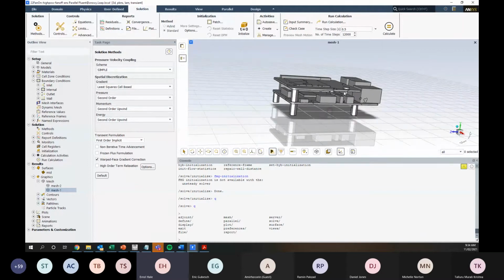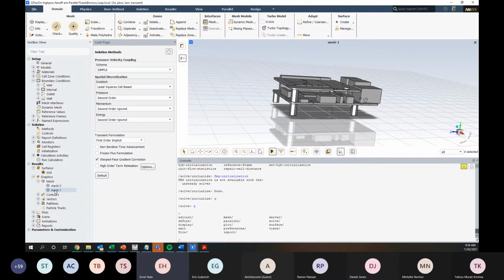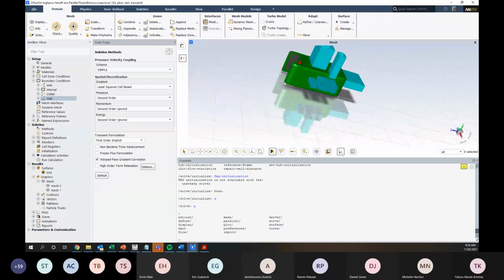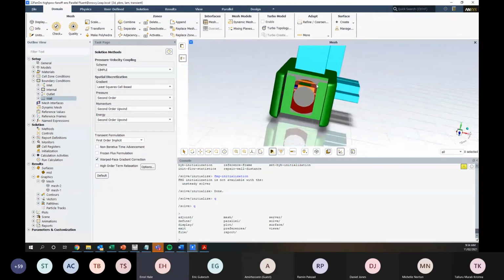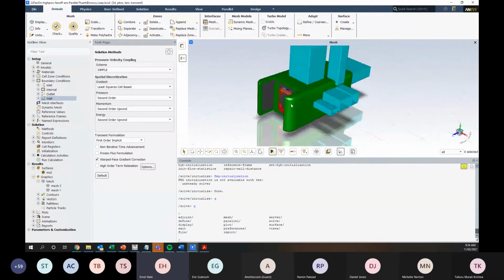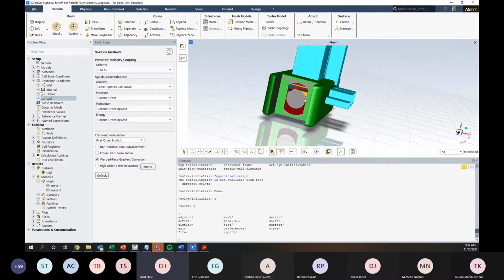So what we did is we built the CAD model of the case with the Raspberry Pi inside, and obviously we generated our mesh, and our domain looks like this. We've got all of our solid components and our fluid domain, and you can see that these outlets extend away from the actual fluid domain on the inside.